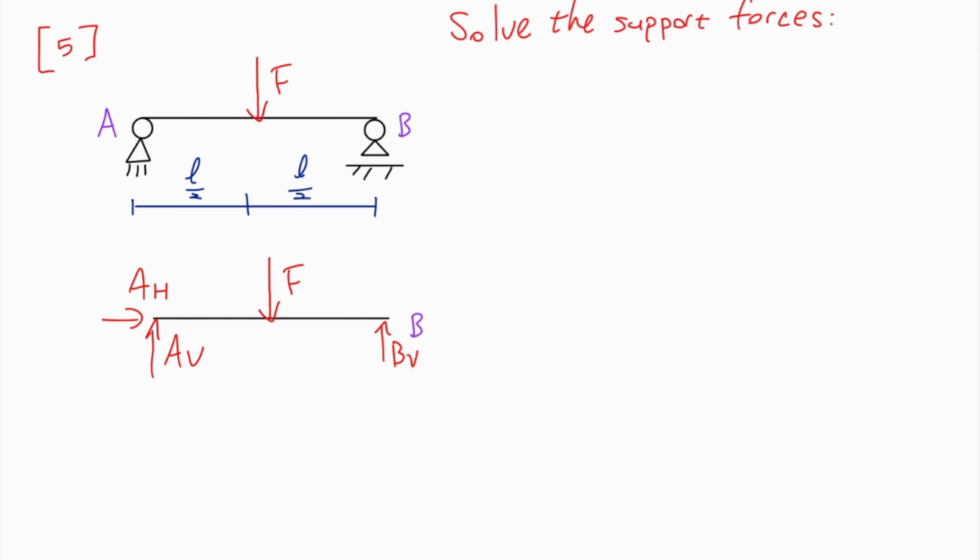There is not a force when the movement is not hindered. For example, B here is a roller support and can translate, so there's not going to be a horizontal force at B. And both of these are rotary joints, or have a rotary joint component on top, which means they allow for rotations. Therefore, I will never have a moment like this. This does not appear as long as my rotation is not hindered. So only what's hindered has to be added, therefore I have these 3 new forces.